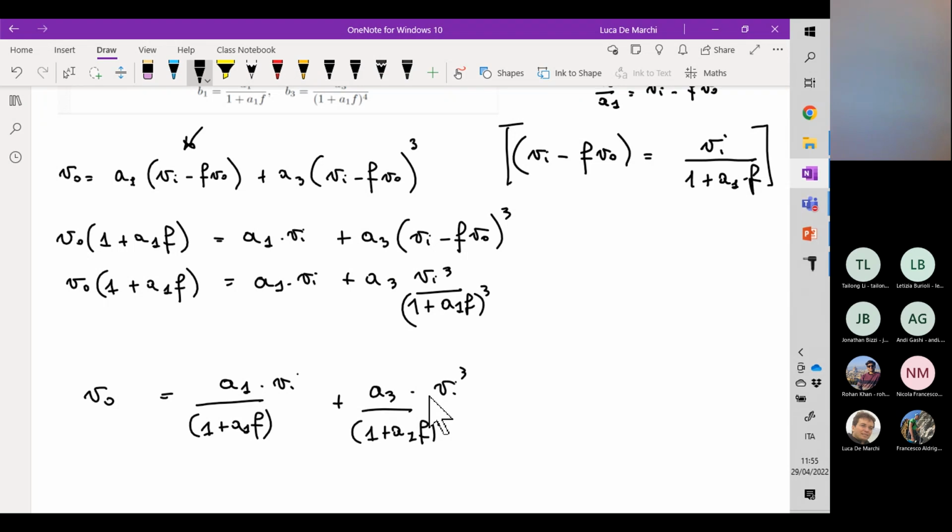So there are some techniques to implement this concept. One way to proceed is to apply the frequency compensation by means of the addition of a new pole, a new dominant pole. This technique is also called narrow banding.